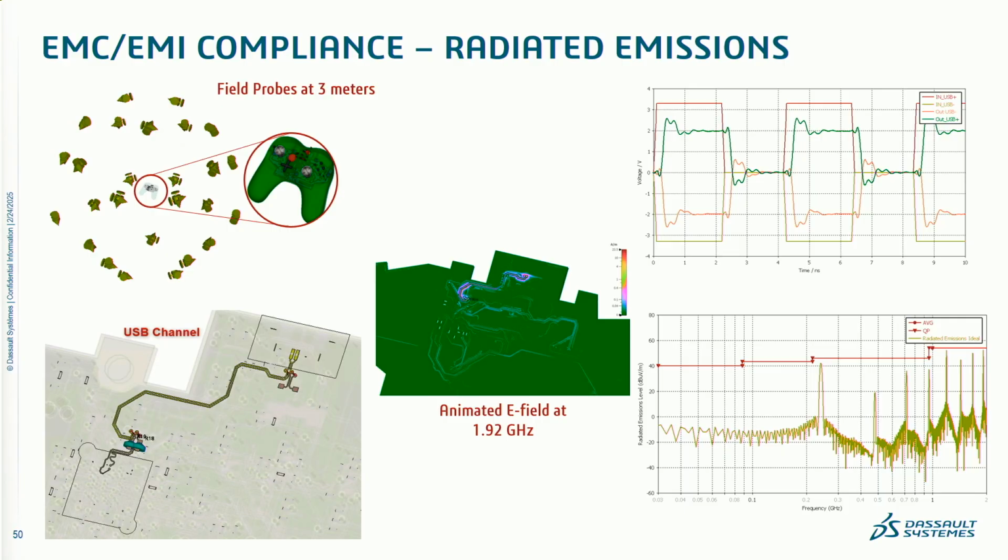Well, if we look at the signal plot up here, what you're seeing, those big square signals, the red and the green ones, a USB trace is a differential pair. So you're sending a positive signal down one trace and a negative signal down the other trace. And you see the smaller, sort of nasty looking lines between them, those are the received signals in there. Again, they don't rise quite as high. They have some overshoot, there's some undershoot. There's a bit of time delay as well.